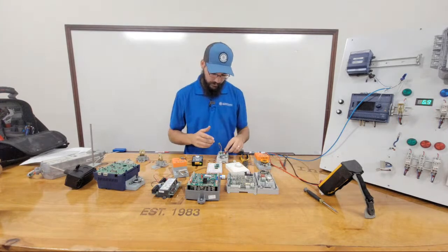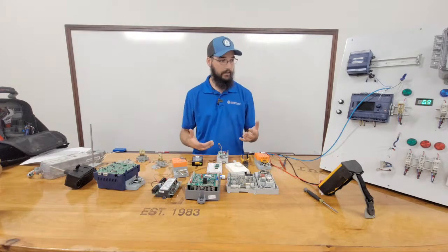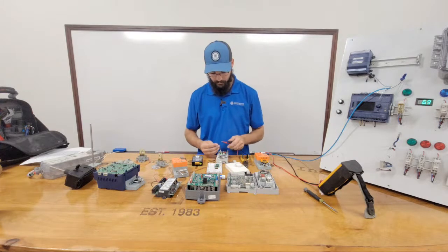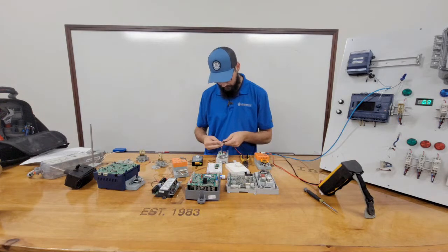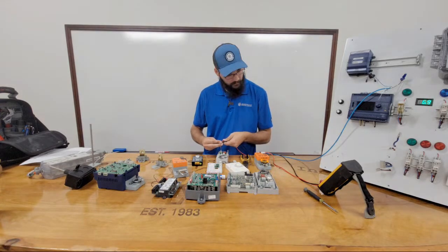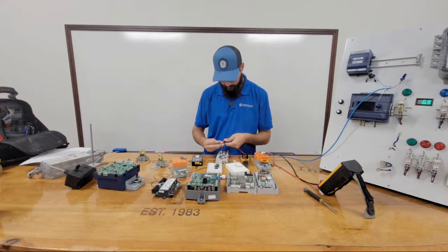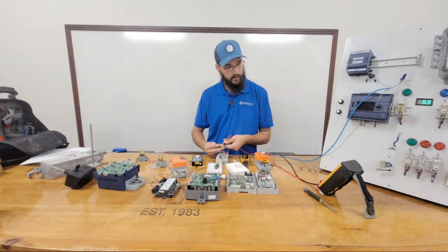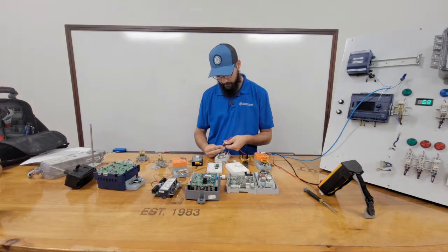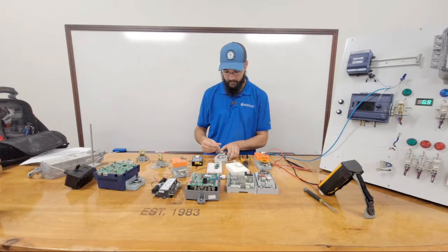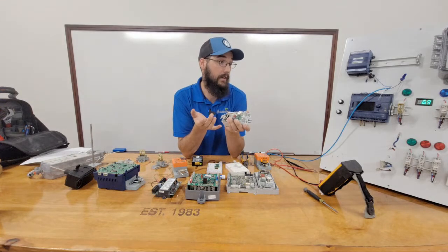So if you ever questioned, okay, is there an issue with that little capacitor possibly? Well, you could do literally what we're doing now. Pull this little green pin off and then test between it. I've got to see which one is which. Not that one. There we go. So terminals 2 and 4 are one stator, and then terminals 1 and 3 are the other stator. And I got the exact same readings.